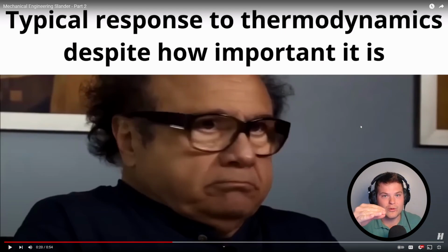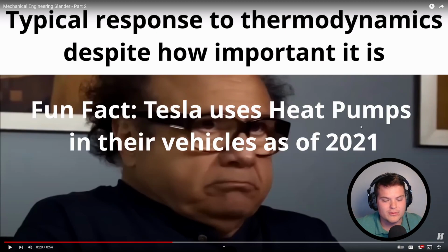You have a cold coil, you have warm air going over it, so you get heat transfer. Your cold freon is absorbing the heat, running it outside to basically another radiator that your fan is blowing the heat out of. So you're basically just taking a block of heat from inside the house and dropping it outside through your AC unit. And the same thing is reversed for a heat pump.